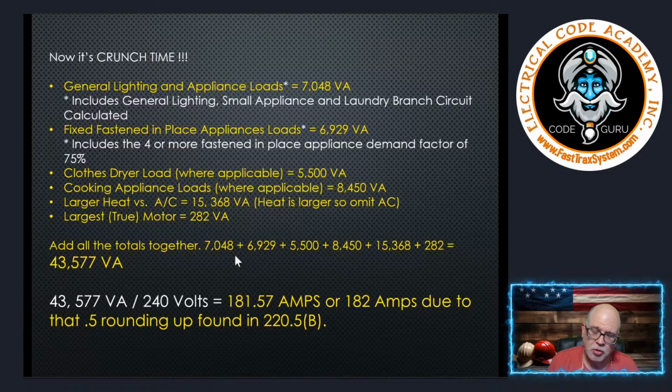In the code, if it's a 100 through 400 amp, 3-wire, 120/240 volt service for a single family dwelling, as in our case, you're allowed to apply some rules in 310.12. We refer to these rules as the 83% rule. This usually yields a size smaller than what you get in 310.16.